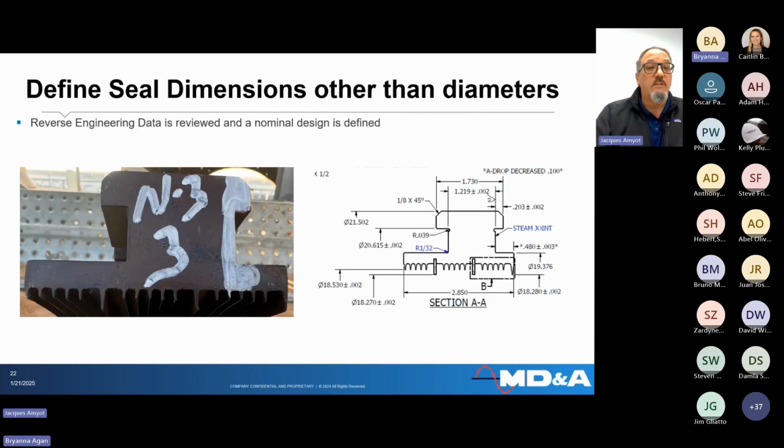And then also reverse engineer the seals, as we discussed earlier. Reverse engineering essentially is defined as capturing, because these seals are around a shaft, they're typically a round seal, so you have a cross section and then you have other features that are unique depending on where you are in circumference. So first of all, we'll define the cross section. Basically the interface with both the stationary and rotating component, the tooth spacing, things of that nature. Obviously, if there's axial clearance issues that we need to disposition by shifting the seal teeth in one direction or the other, we'll figure that out as well.